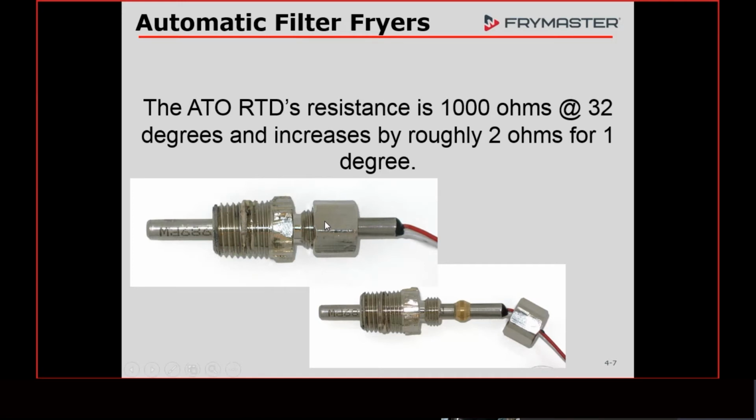The only thing it can be is that we don't have the right resistance going back, or the board, in this case the ATO board, is just not processing that information properly. It would be an easy thing to troubleshoot.